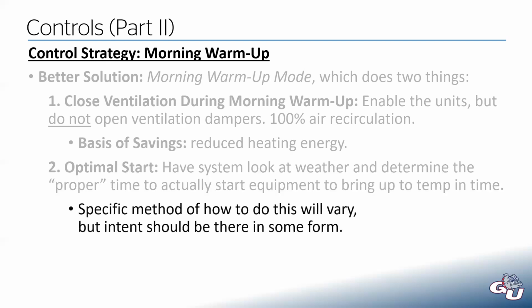The specific method for how to do this can vary a little bit, but the intent is the same. You have to have some kind of programming in place that will dynamically change the start time to bring your building up to temperature at that occupied start time.